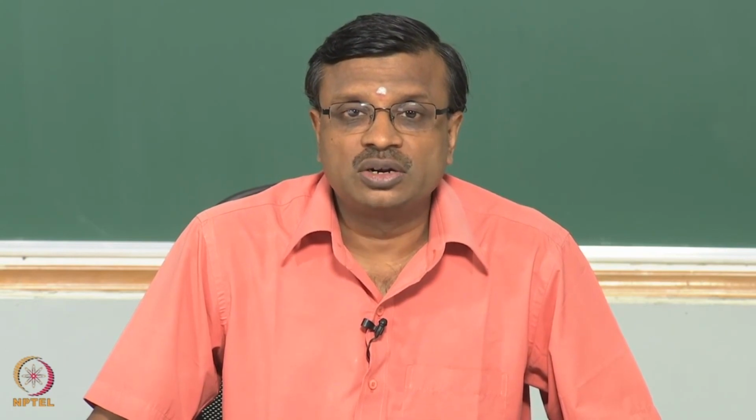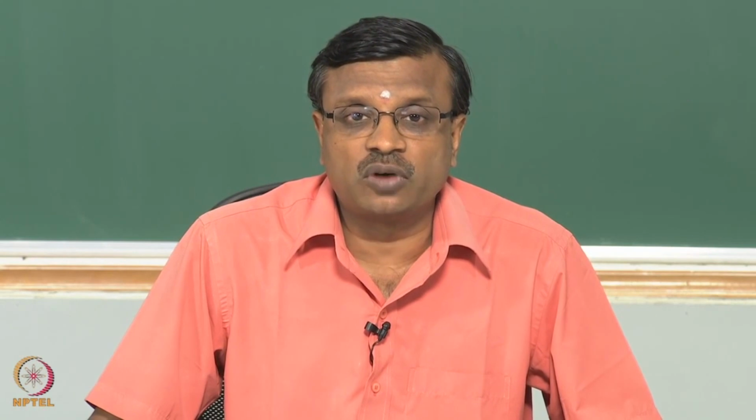We also learned a couple of other things, how to proceed to get the solution, the segregated solver and the simultaneous solver. There is also one more technique called the under relaxation technique, which helps in fast convergence. With this, we come to the end of this week's class.